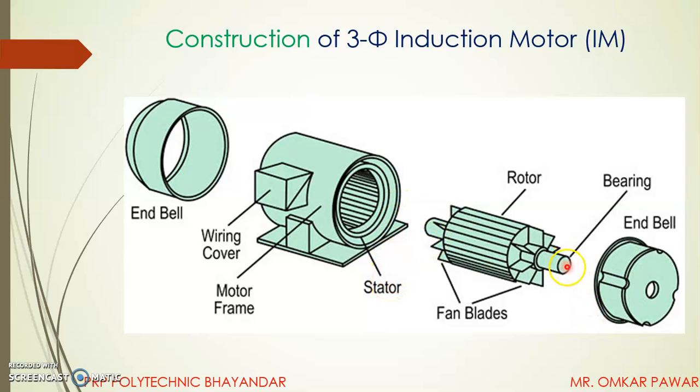Next is the shaft, and on the shaft the rotor is mounted, which is the rotating part. Next are fans to cool down the machine, and end bells, that's it for packing, and a wiring cover to feed the supply to the three-phase stator winding.